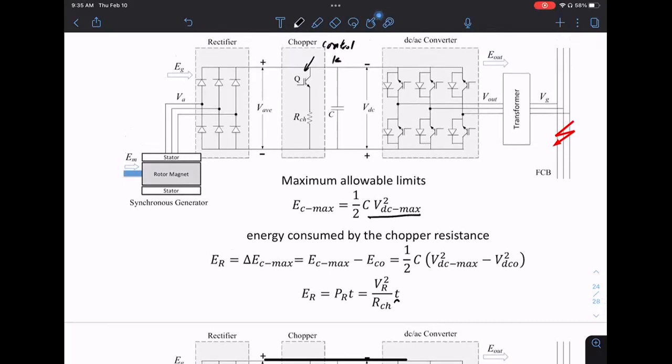Because the resistance is a fixed value that doesn't change, the way you get a varying resistor is by controlling the duty cycle. By controlling the duty cycle, you can control the effective resistance through this line. The assumption is that the switching frequency of this switch is high enough that you can just look at the average value of this resistance.